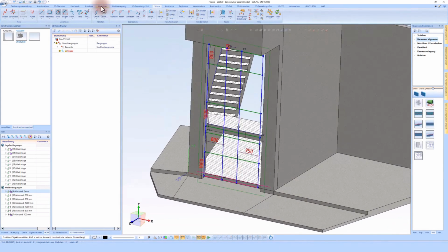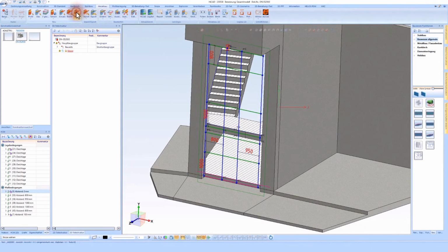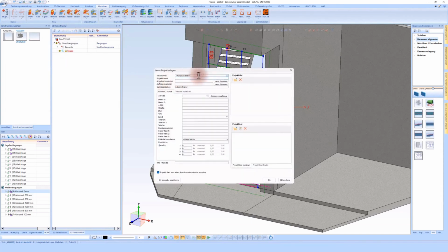So the next step is to just generate this facade here. This means I select the command with the sketch and need to confirm this sketch. Here I can decide whether the sketch should be deleted or not. In this case, I want to delete it deliberately, because I can always modify it later. So now I am asked if I want to create a new project in Logikal, which I do in this case. And now the interface to Logikal is being loaded.